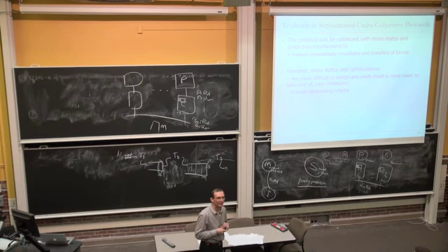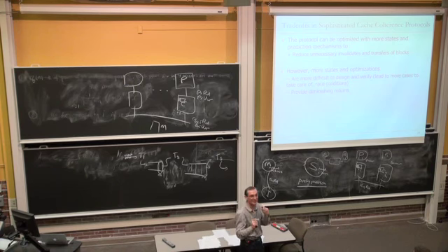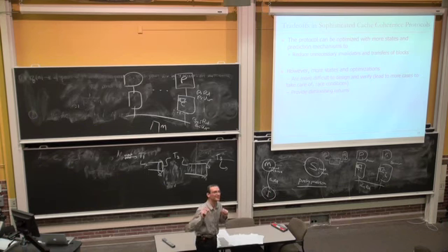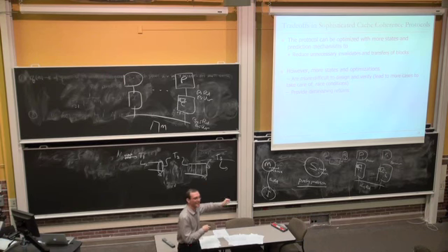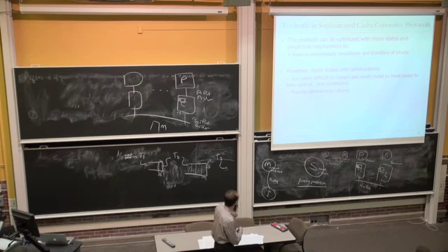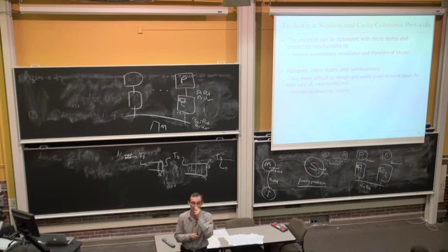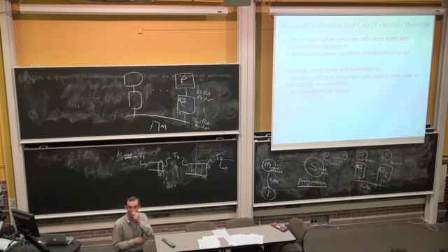When my TAs designed the lab, for example, they tried to make it as easy on you as possible so that we minimize those potential race conditions, because requests complete at different times, right? So you need to make sure that the state transitions happen at the correct time. So those race conditions need to be handled correctly. And as you have more states, more sophisticated protocols, and prediction mechanisms, those become harder to handle. Okay?